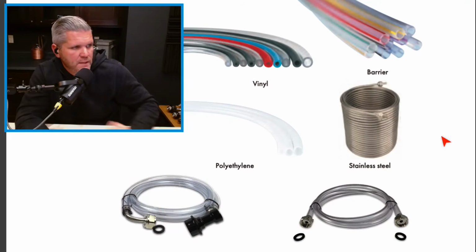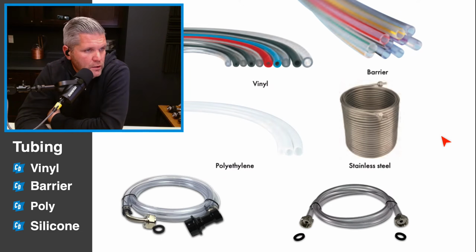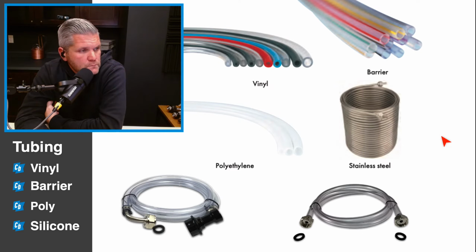So from the keg, then we're going to go up through the coupler because the gas is feeding and pushing down on the liquid that's inside of the keg, and the liquid's going up through the spear to the coupler again, and then out to what would be tubing. So there are 3 types of tubing. The main tubing coming off of your coupler is going to be what's called your jumper. So the jumper connects to typically barrier tubing, and then the barrier tubing connects to choker line.